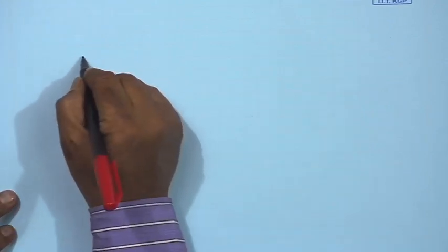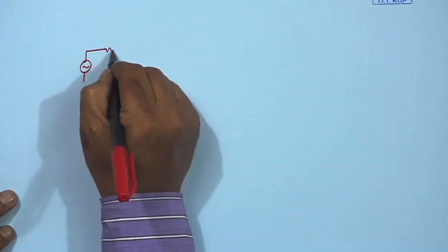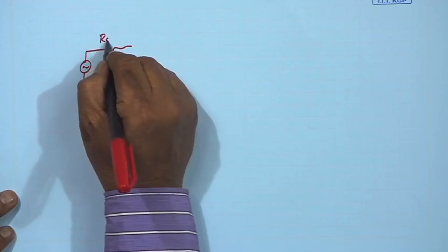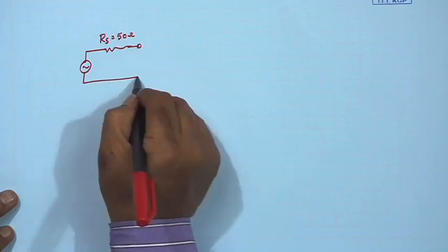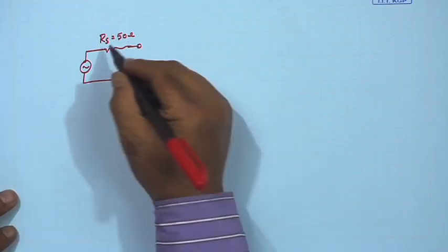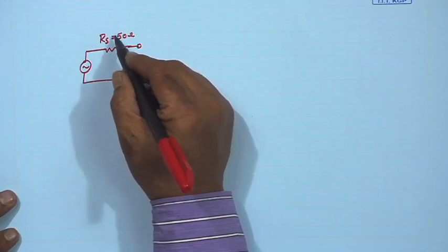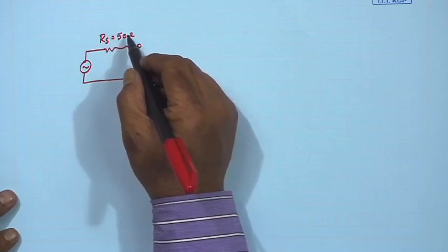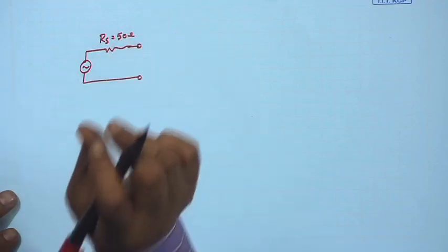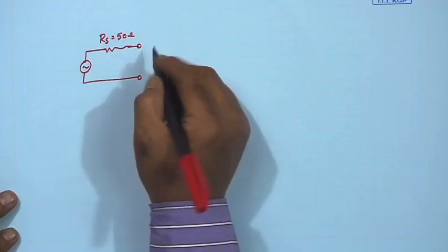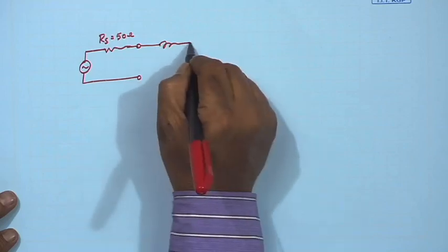So, I can draw that this will be the circuit. I have the source, then the source impedance that has been set to be 50 ohm. This is a Butterworth filter. So, in the prototype it is assumed as 1, that means G0 is always 1, but here it is 50. So, we need to scale with 50 at the appropriate time, that means our unknown value multiplier will be 50, and then we know the first element we can choose as L1.